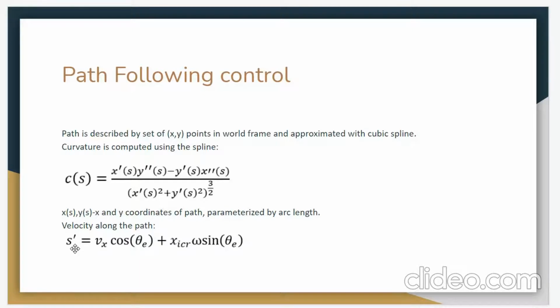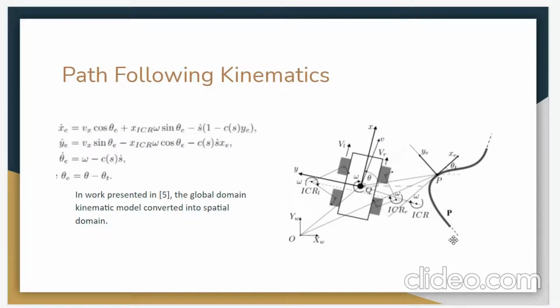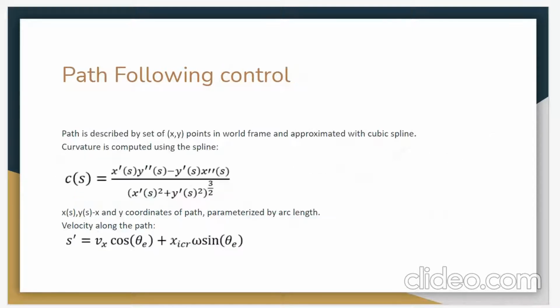So with this target set, the robot will follow the path as it will try to minimize the deviation from the virtual vehicle position, which is always on the path, and actual robot's position, and also target a certain velocity along this path. Thus, the robot should be moving along the path with designated velocity, if possible.